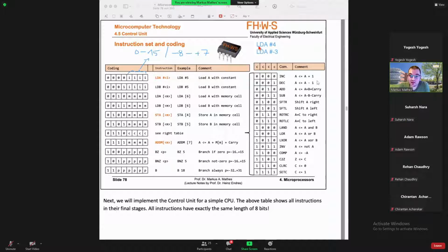So you can state, for example, LDA immediate 4 or LDA immediate -3. For each, a bit pattern is created. A 4 is 0, 1, 0, 0, and a -3: this is 0, 0, 1, 1, inverted 1, 1, 0, 0, plus 1 is 1, 1, 0, 1. So the 2's complement for -3 is 1, 1, 0, 1. But both are simply bit patterns. So the interpretation is up to you. Keep this in mind if you write your programs, that you have to handle if this is signed or unsigned.